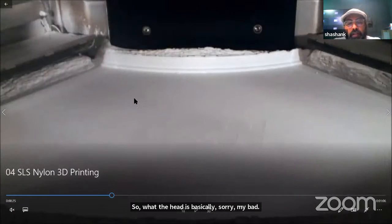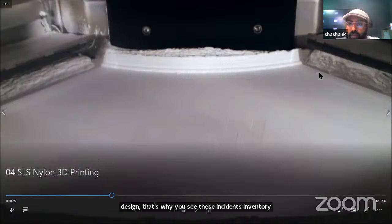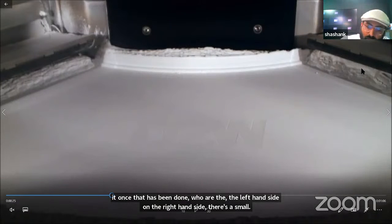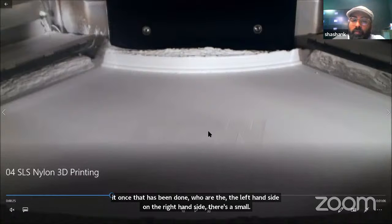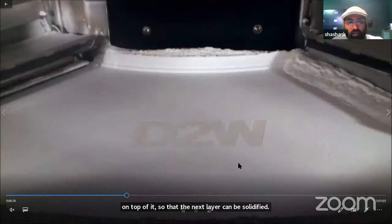Okay, so what is happening is, from the top, the laser comes in and just solidifies a certain area of your design. That's why you see these indentations to it. Once that has been done, on the left-hand side and the right-hand side, there's a small hand which comes in and flows in the material on top of it, so that the next layer can be solidified. So that is what you're seeing, the left and right movement of the hand.